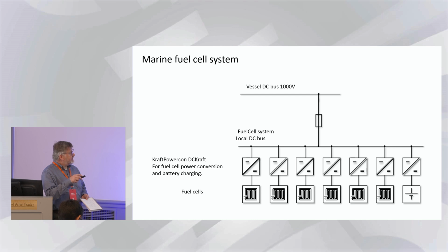So we need a DC-DC converter before every fuel cell, before they are put to the DC bus. And because of the impedance to ground in every fuel cell, that is not negligible, it's very beneficial to have galvanic isolation in the converter. For the batteries here, they must also be charged, so the power flow must be bidirectional.